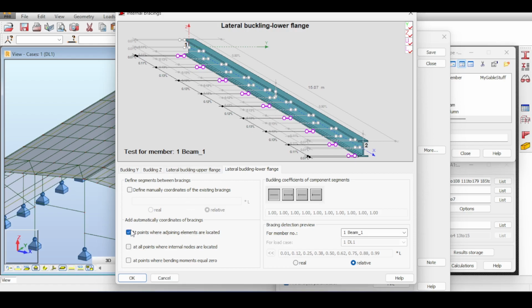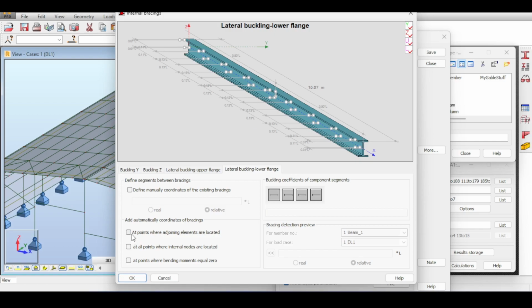And you're right. So I will not let it brace the lower buckling flange. I will only let it brace for general buckling and top buckling, because the bracing between the purlin and the rafter is only going to be targeting the top side, so I don't believe that the bottom side is braced.